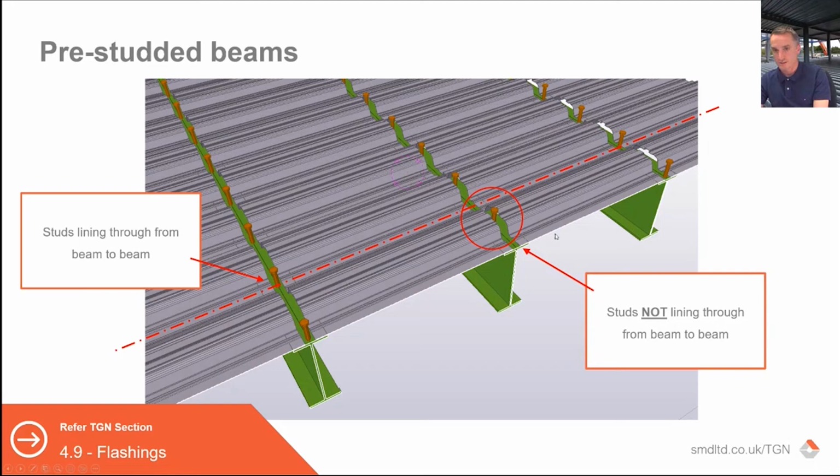Obviously it creates a much better way of justifying that stud resistance, because you do then end up with a larger concrete section, and you can potentially look at that beam differently depending on what the flange width is and depending where your deck bearings are and the crushers are. But you potentially have a wider concrete section that is then solid down the center of the beam. So it's something that can be looked at, but the important thing is just to coordinate the two.